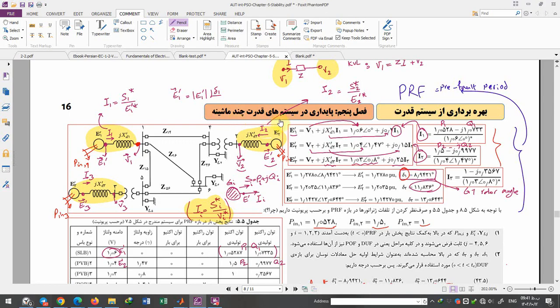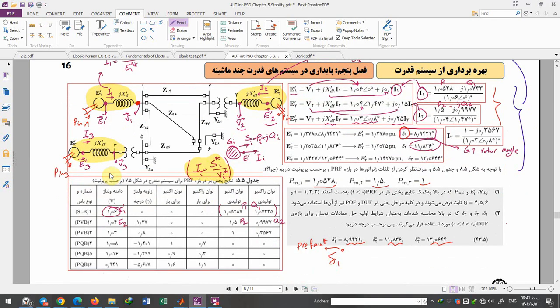is found from running load flow. For that situation, in the main question, we give you the result of power flow in this column. The magnitude of voltage in each bus is achieved from running load flow, and it is an input of each question for solving stability.